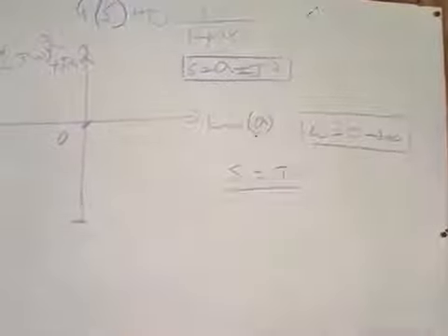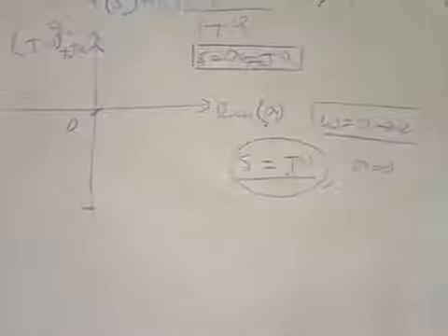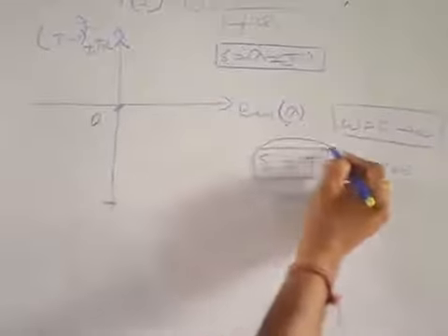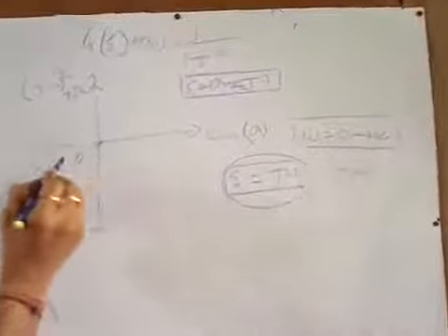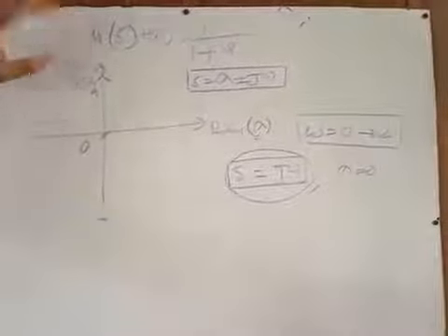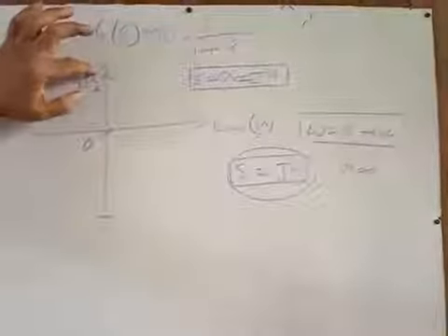If you put s equal to jω, then on this jω axis the real value at every point is equal to 0. So everywhere you find sigma is 0. So this imaginary axis has the equation s equal to jω. Now if omega is varied from 0 to infinite, that means from say 0 to a certain point A, and A is at a very large distance, so this can be taken as the infinite point.